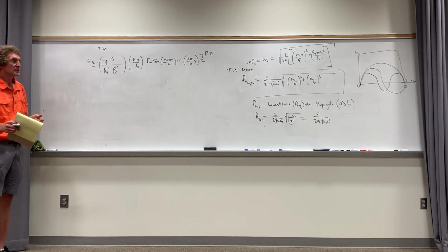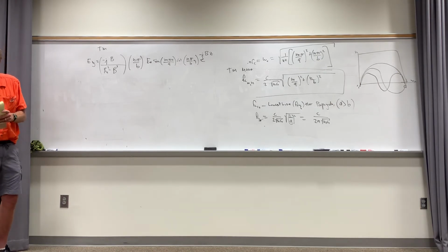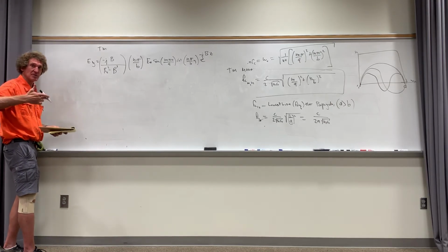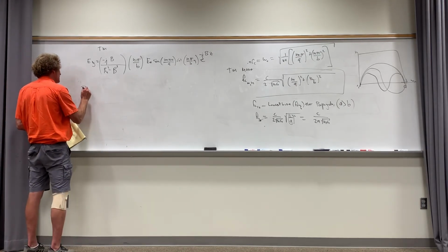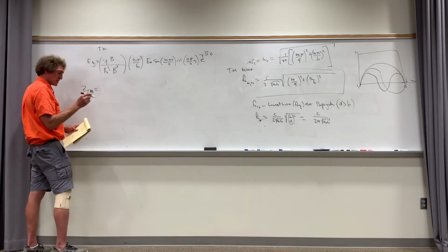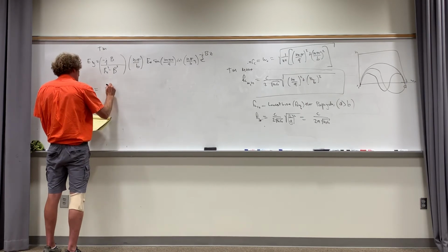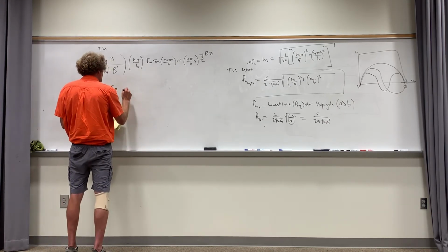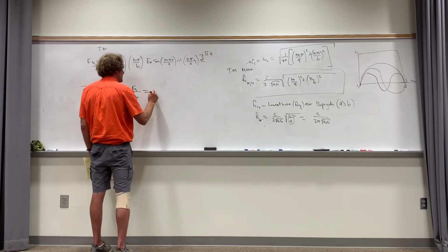Well, in a transmission line, you had something called the characteristic impedance. Do y'all remember that? Here we have something that is likened to a characteristic impedance. It's an impedance in that mode that the guide sees, and it's a ratio of the E field to the H field, which will always be a ratio of the voltage to current that would come on any load connected to that guide, and this is important. So then we get Z in the TM mode. TM, this is going to be equal to, really it's minus, it's plus EX over HY, or it's minus EY over HX.